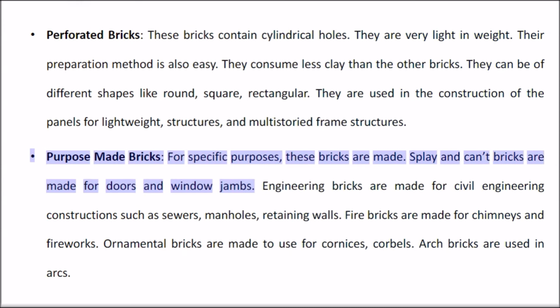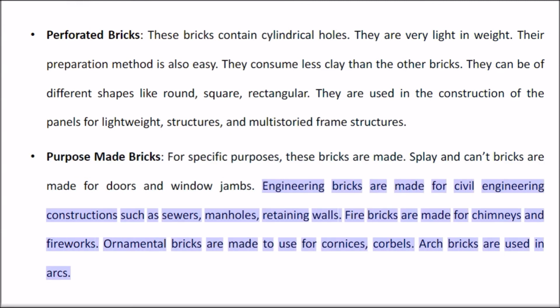Purpose-made bricks. For specific purposes, these bricks are made. Splay and cant bricks are made for doors and window jambs. Engineering bricks are made for civil engineering constructions such as sewers, manholes, retaining walls. Fire bricks are made for chimneys and fireworks. Ornamental bricks are made for use in cornices, corbels. Arch bricks are used in arcs.